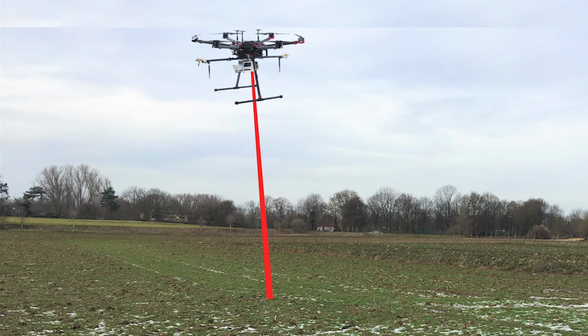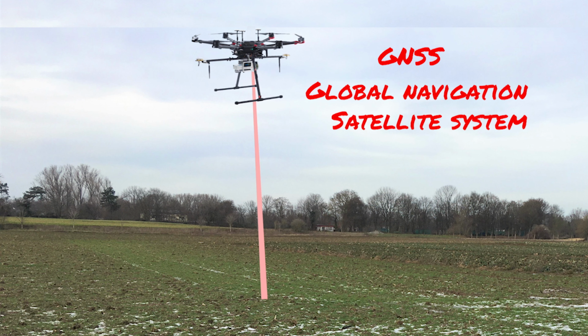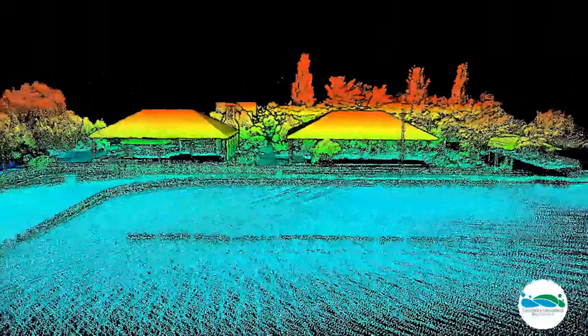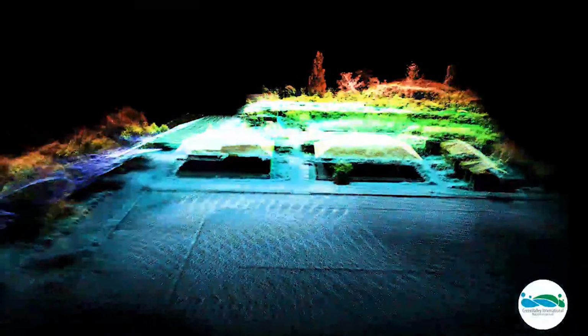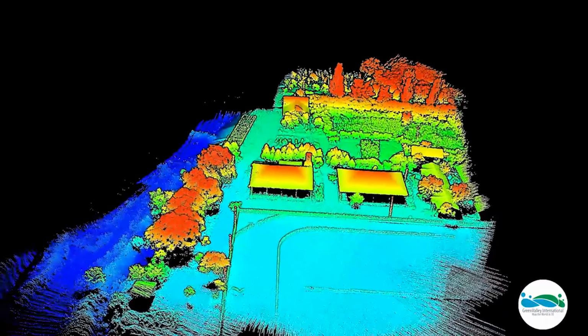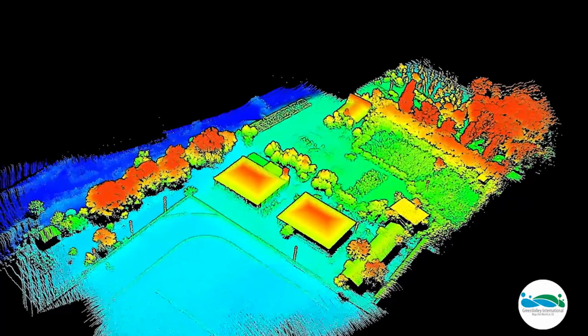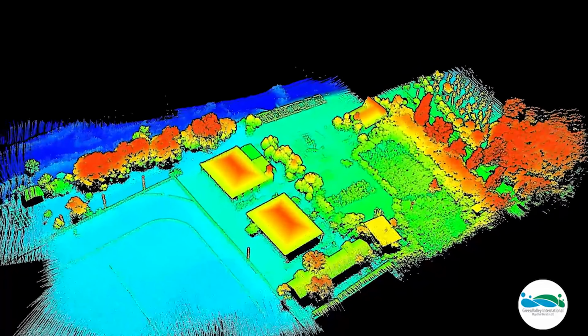A LiDAR scanner also includes critical information from an inertial measurement unit, or IMU for short, where it records pitch, roll, and yaw parameters, while a GNSS unit records the positioning of the sensor. All of this data is then integrated with the LiDAR results to create highly accurate data measurements. Naturally, there is a lot more to it than that, but that should bring you up to speed on the basics of how a LiDAR system operates.